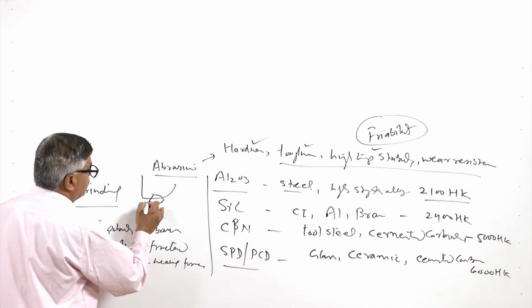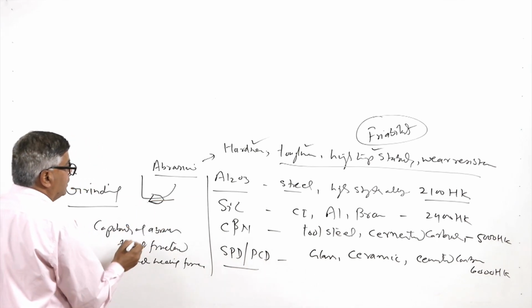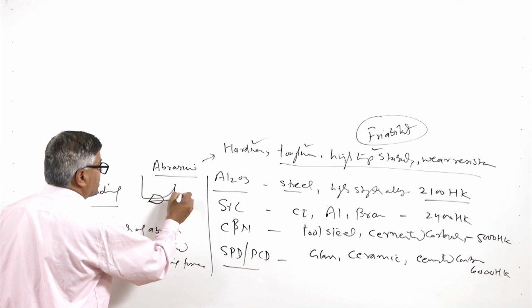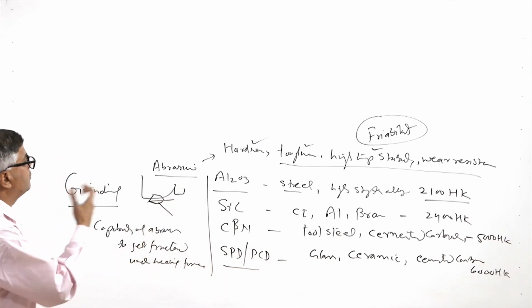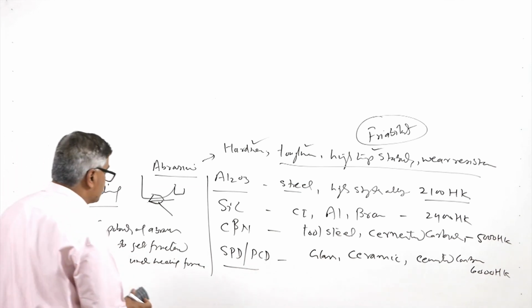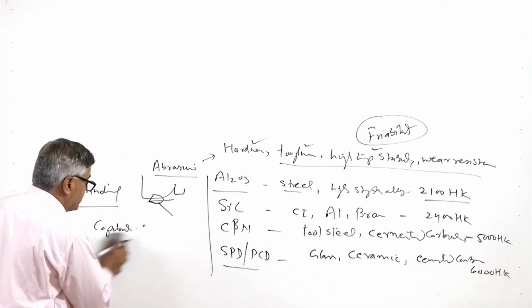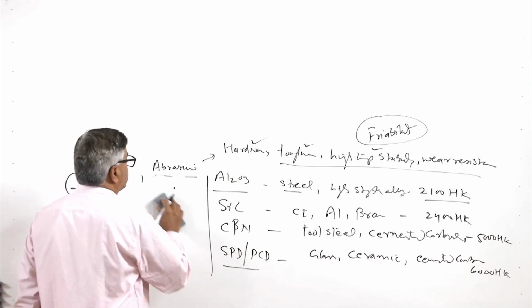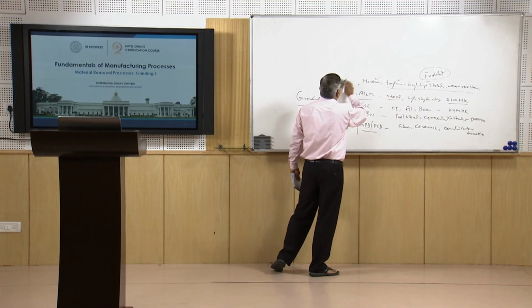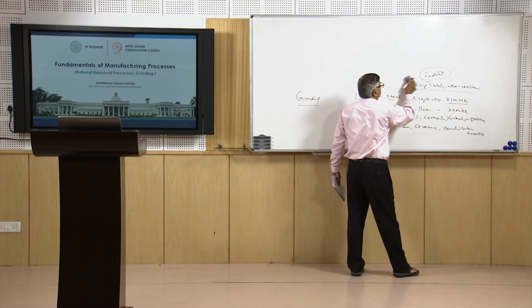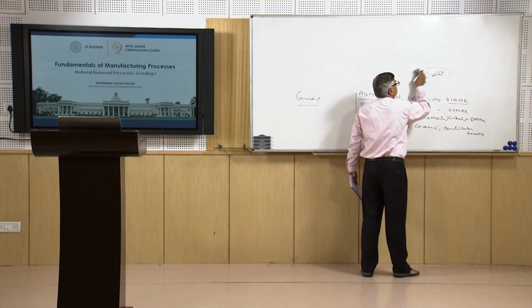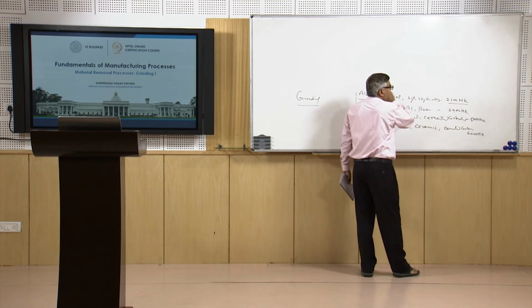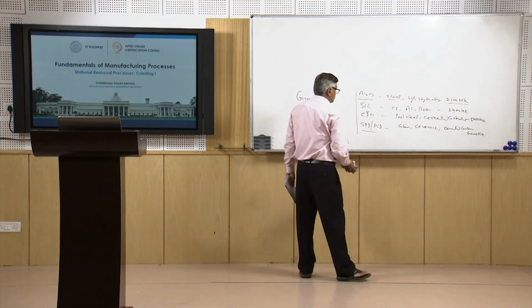So, under those heavy forces, if it gets fractured, it will be producing the fresh cutting edges. So, fresh fracture of the abrasives will be leading to the formation of the fresh cutting edges. The formation of the fresh cutting edges due to the fracture of the abrasives is governed by the friability of the abrasive. So, for the grinding wheel it is important that the friability of the abrasives is good, so that it can maintain its cuttability.